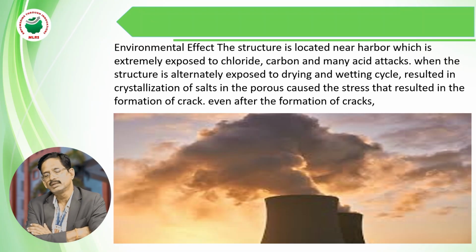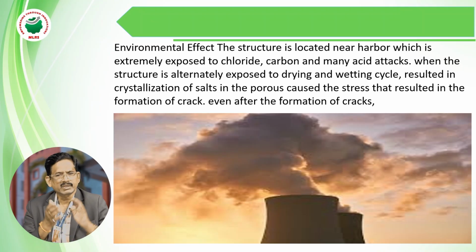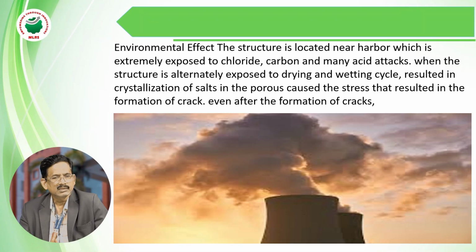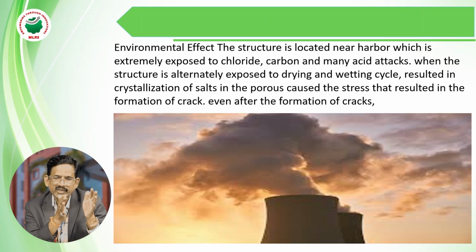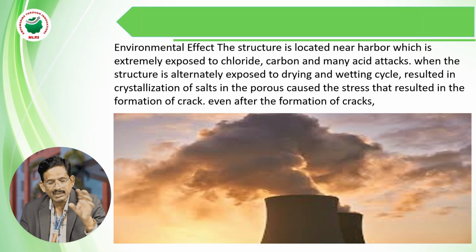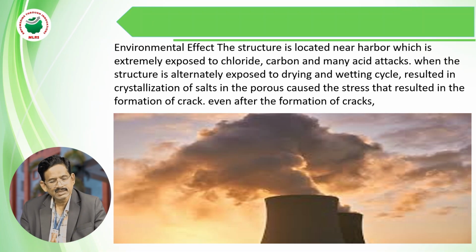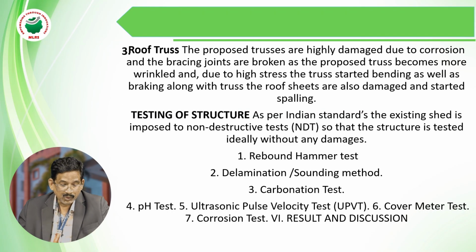Because of the environmental effect, this site is located near the harbour. Because of the salt water in the sea, the chloride content will affect the concrete itself. So, because of the drying and wetting cycles the concrete is subjected to, some cracks will develop. That is the environmental effect. So, we are seeing wider cracks, hairline cracks, this environmental effect, and another thing is the spalling of the concrete. Next, we will go to the roof truss.